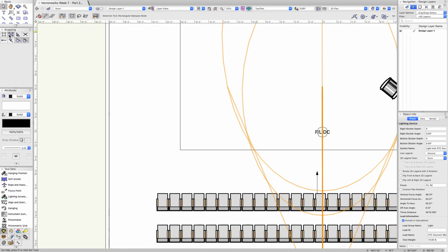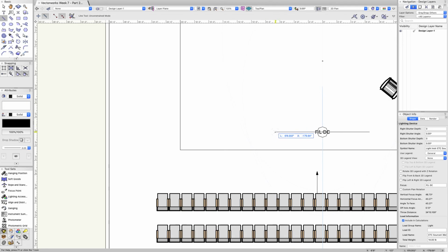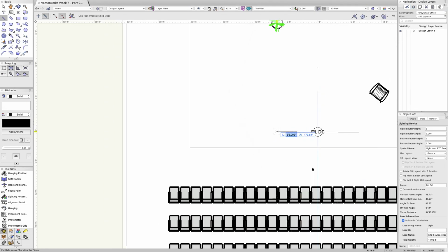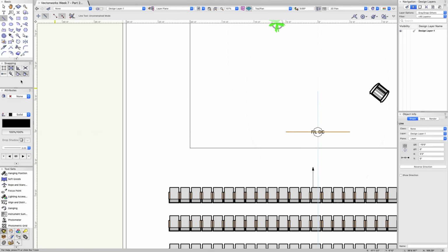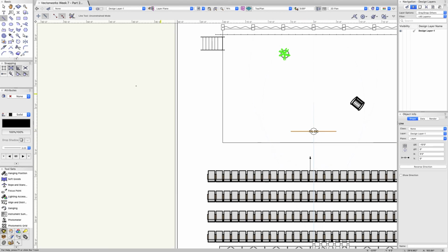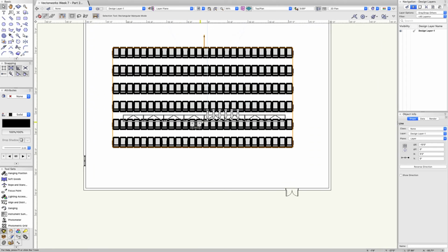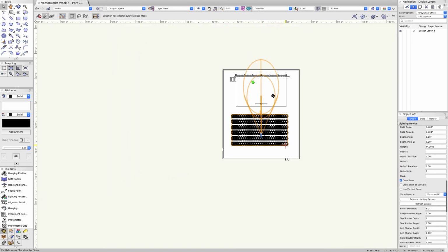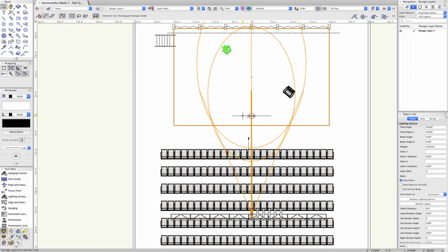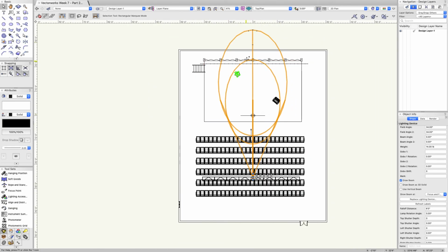And so at this point, I want to measure across. We say that we generally want a light to cover about 10 feet. So if I go here, and because I'm using the double line tool, I'm just going to hit 5 feet and put it at 180. Need to turn on some mapping. All right, so that's about a 10-foot line in between, and you'll notice that light is a little bit too big, right? And also it's going way off the back here.